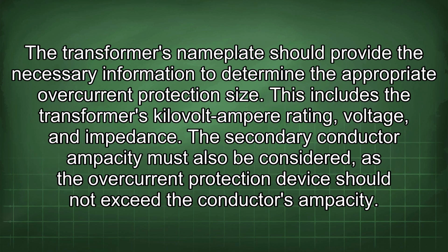The transformer's nameplate should provide the necessary information to determine the appropriate overcurrent protection size. This includes the transformer's kilovolt ampere rating, voltage, and impedance. The secondary conductor ampacity must also be considered, as the overcurrent protection device should not exceed the conductor's ampacity.